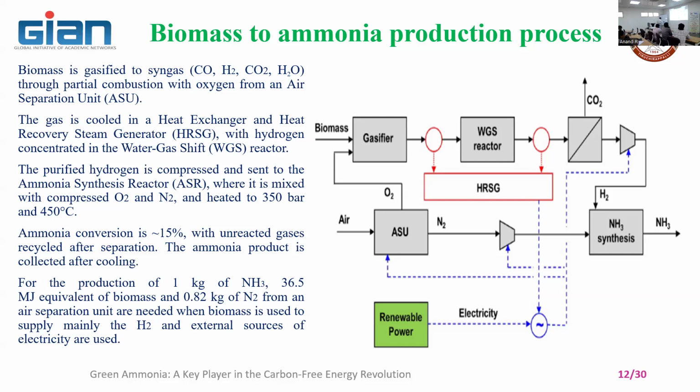It's an online system calorimeter. You can measure how much energy is going to be liberated when you burn unit volume of the fluid. That is very important. If you talk about the gas, the unit is megajoule per meter cubed. If you want it in terms of megajoule per kg, you need to multiply by the density of the gas, corresponding to the temperature of the gas leaving.